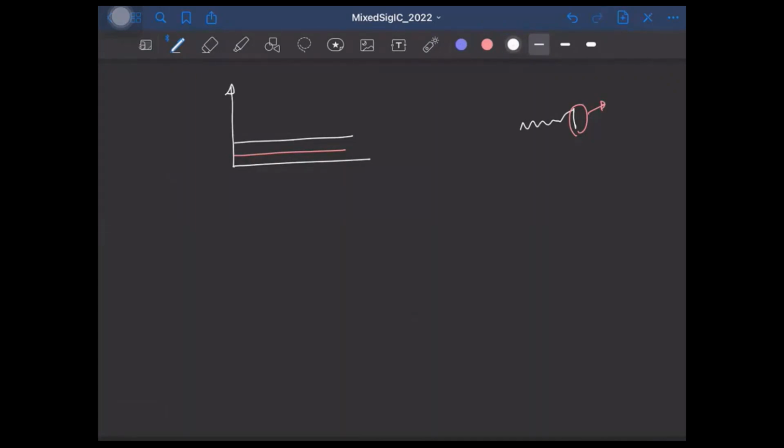But as we'll see in later classes, we'll be dealing with a special kind of ADC called noise shaping ADCs, where the noise spectrum will not be flat. So how it will look is as follows. If we give a sinusoid, we'll have one sinusoid here, and the quantization noise will be high pass shaped and it will have a spectrum like this.